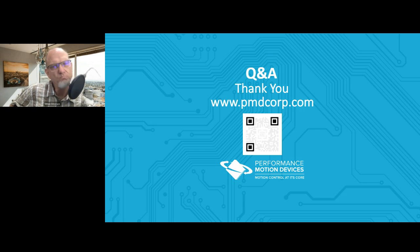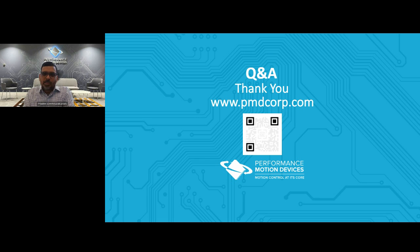Yeah, so what we've seen is if you take the big robotic arms, most of them are centralized. So they have an external CPU, right, a controller. They do field bus or EtherCAT to the drives, and the central controller is doing all the profiles and the motion planning and all that, and they send PVT points to the individual nodes. So which works well when you have a lot of space for a bigger CPU.